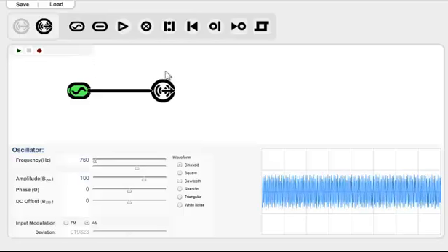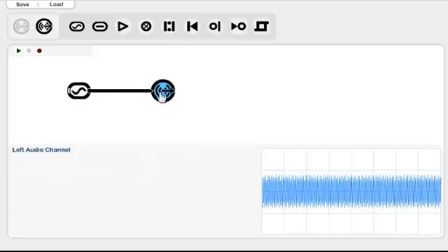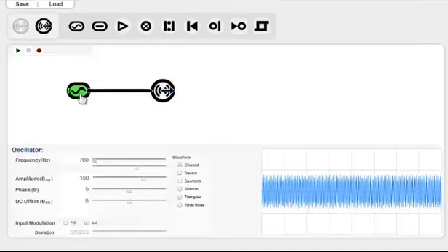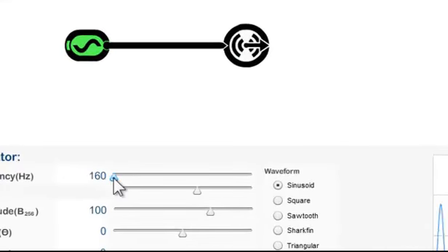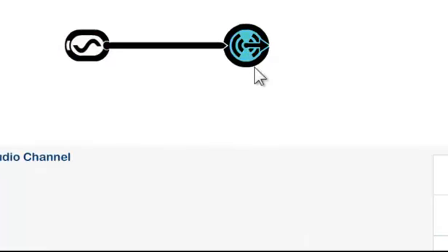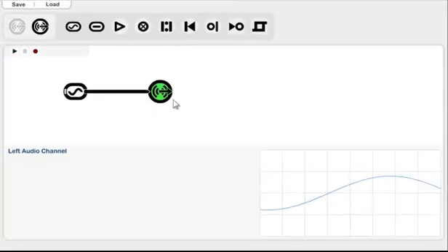Now, just to get an idea, in future development, say if this was a motor, a DC motor or a stepper motor, rather than a speaker, by applying, let's say, a low frequency oscillation, something like 1 or 2 hertz, you would get a motor to sort of turn forward and then backwards, and by attaching the motor to, let's say, a limb of a robot, you would cause the leg to move back and forth and so forth.